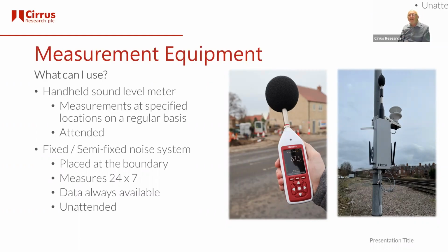The disadvantage with that is you're not going to pay somebody to stand there and do that all the time. So you might do that maybe once an hour, go around all the points once an hour. You've still got the expense of employing somebody to do that, and you're missing all of that noise in between. So handhelds can be used in certain situations, and there is an advantage because you're actually there listening to it. But the disadvantage is you're missing out on what's happening at other times, because construction noise is variable, and if you're not there constantly, you will miss certain things.